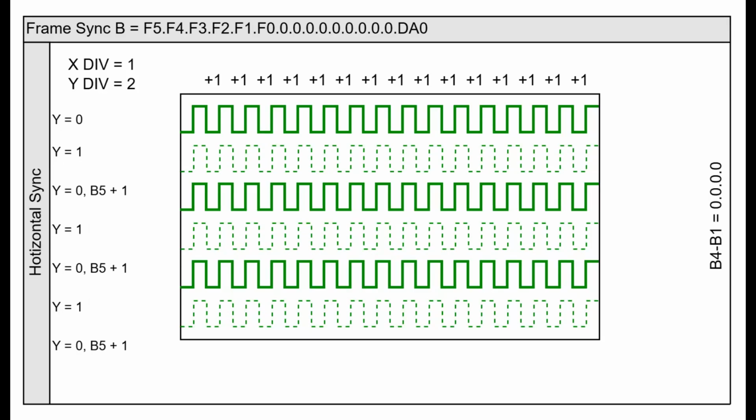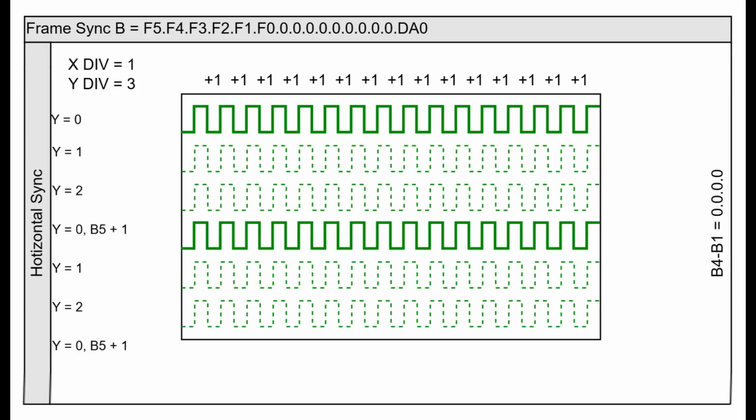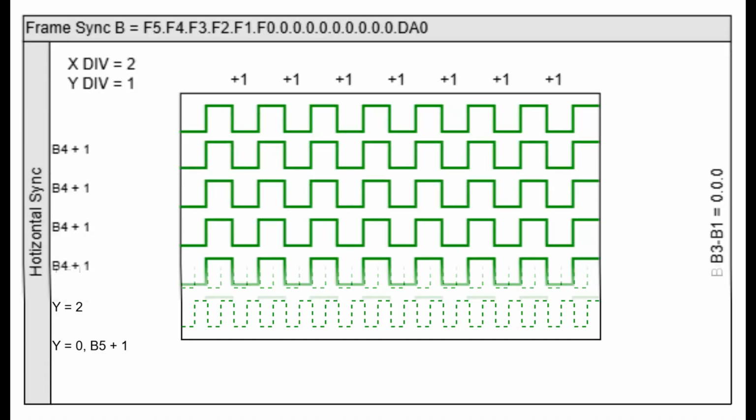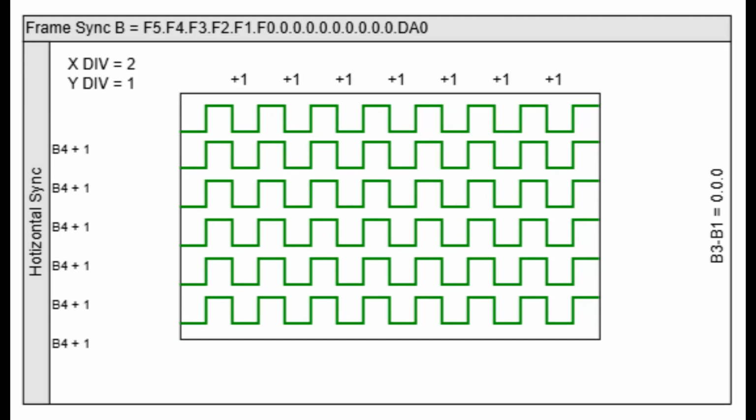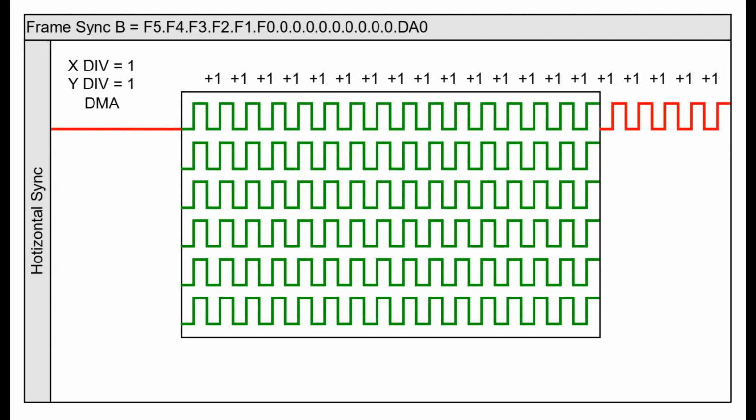Remember this nugget. If the least significant bit of the video mode register is clear, the SAM will clear bits 1 to 4 of the video address register, effectively giving the register a 32-byte resolution on a horizontal sync. If the same bit of V is set, only bits 1 to 3 are cleared, which equates to a 16-byte resolution. If the row is set to repeat, the next uncleared bit is preserved, otherwise the address increments as normal. When V is set to DMA, no bits are cleared at all.